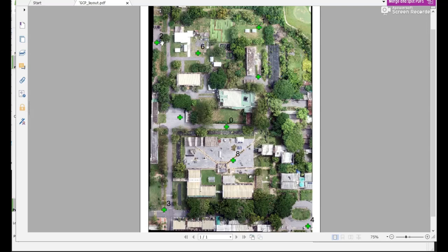We used a high precision RTK GNSS unit. Our ground control points would be points 1, 2, 0, 3, and 4, altogether 5 GCPs. AIT is a relatively flat area, so we can use 5 GCPs. 4 in the corners and 1 in the middle would be sufficient.